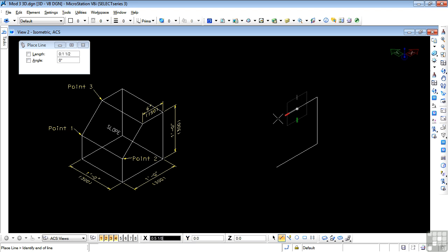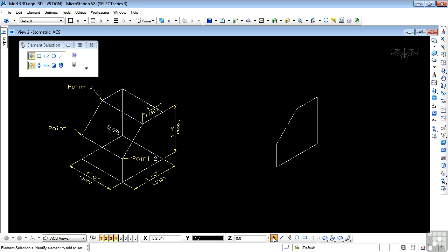Left click, drag down. Need to find the point now above the starting point here, 6 inches up. So I'll go down to here. AccuDraw is on, so I can press O to put the compass there, drag upwards by 6 inches, and again, find the previous distance marker, left click, and just drag straight down. And we're done.